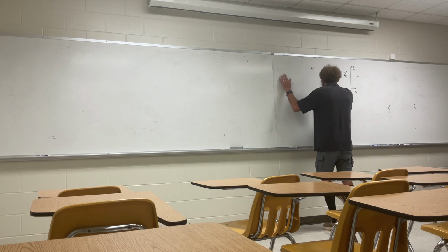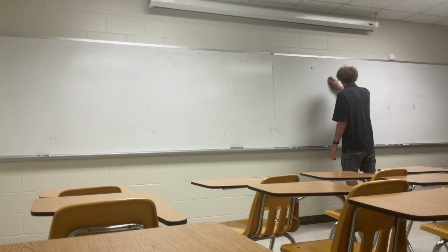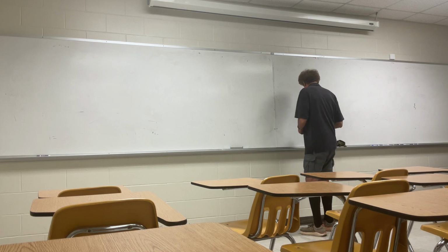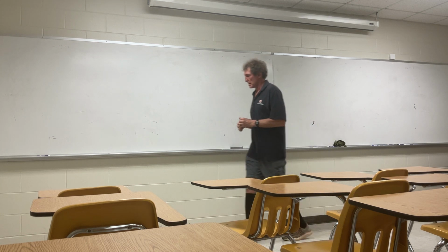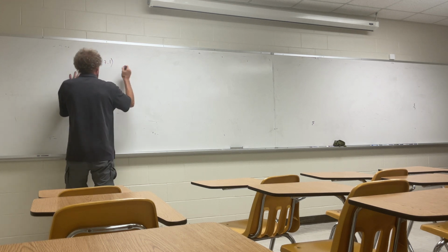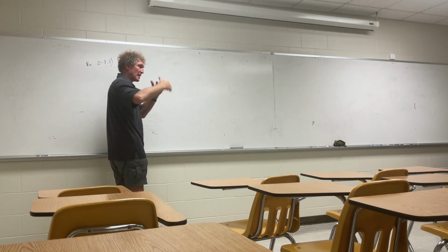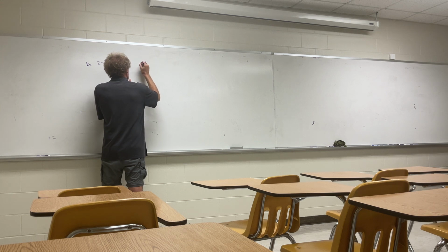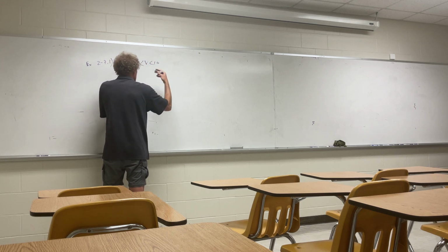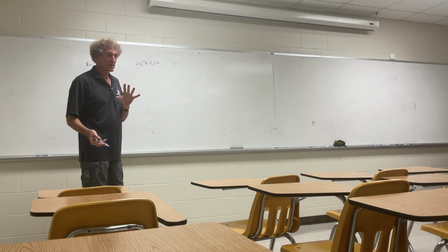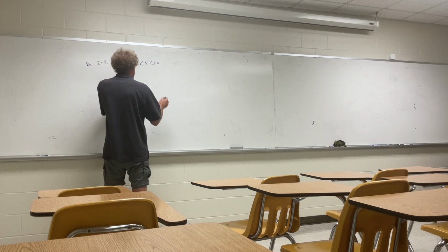You'll need to know that variance and standard deviation for a uniform distribution. So for this one, this is exercise 2-7.1. He gives you a range, a V, right? Between 0 volts and plus 10 volts. Okay, that means the total span is 10 volts. Do y'all follow me? If it was minus 10 to 10, it would be 20 volts. Clear, class? Then he says, how many levels?